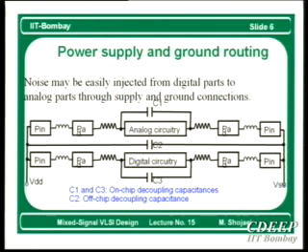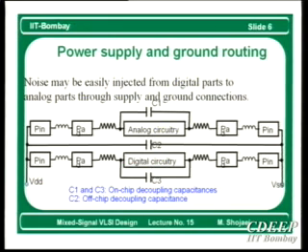Now, where are inductors? Inductors are important when I have a pin connected to a pad through bonding wires. This is a bonding wire. Here is where I have a problem. See, the same scenario I showed you in the previous slide: there is an inductor in series between pin and pad. This is bonding wires, okay? Then this is just considering, okay, it is a VDD. It can be a high frequency signal. There will be similar impacts.